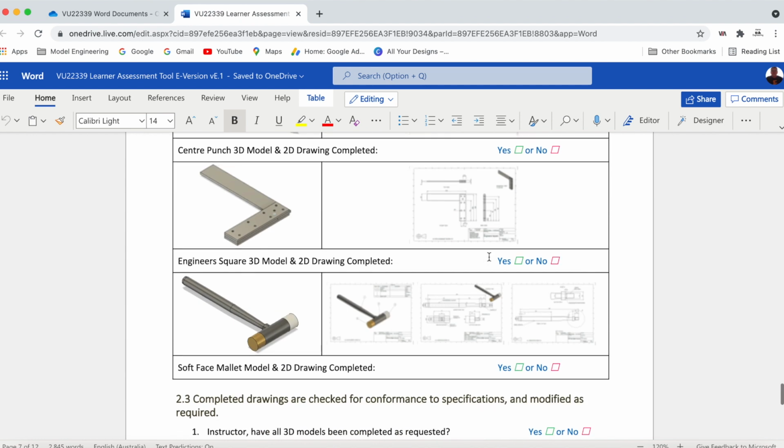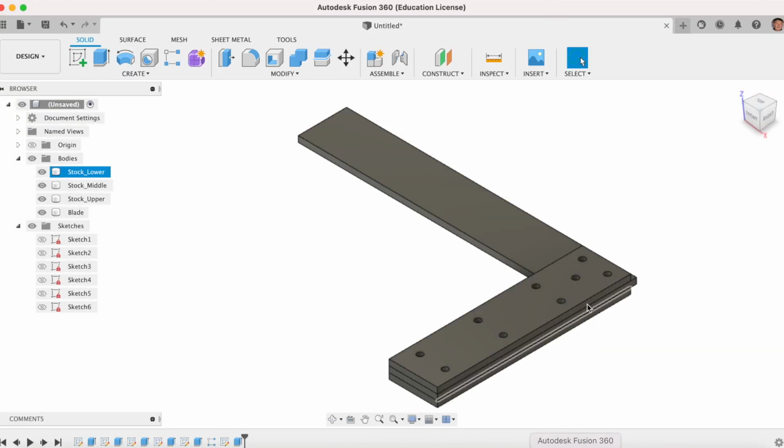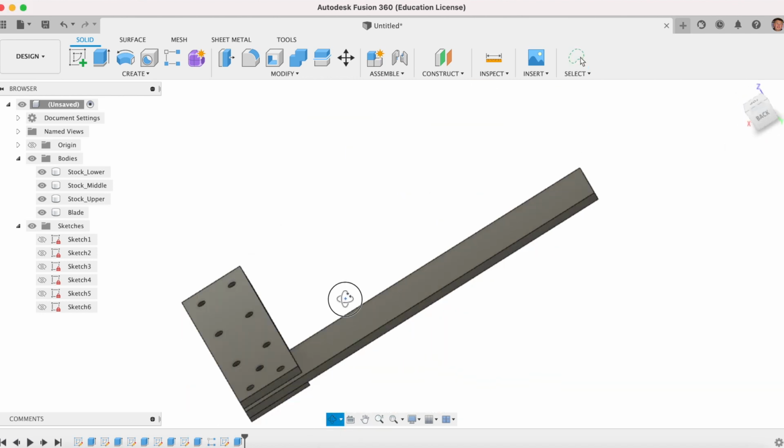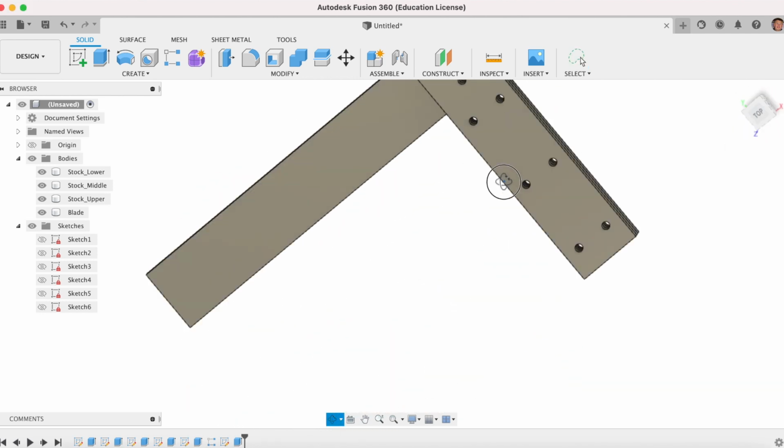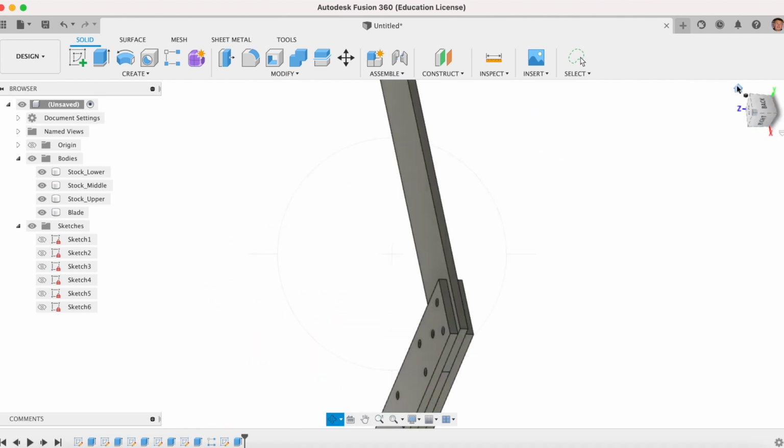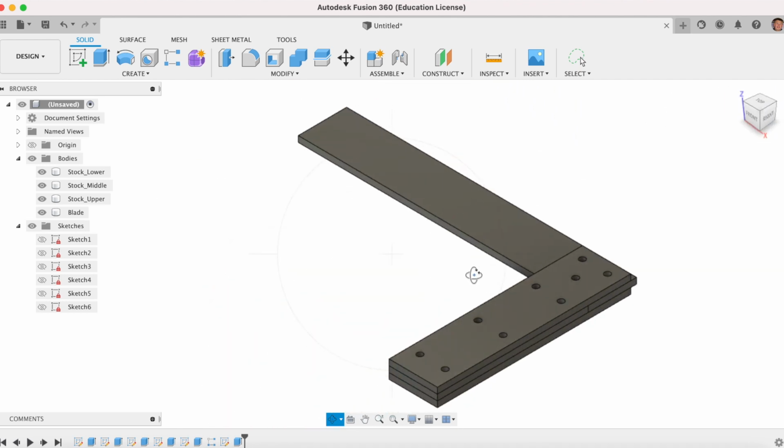So let's get started. Let's open Fusion360, and here's the model that we will need to do today. If I free orbit that around, you can have a look at it. Now, this isn't an assembly model. It's just purely a normal parametric 3D model. And every time I've done an extrusion, I've created a new body, and the new bodies can be seen here in the tree.